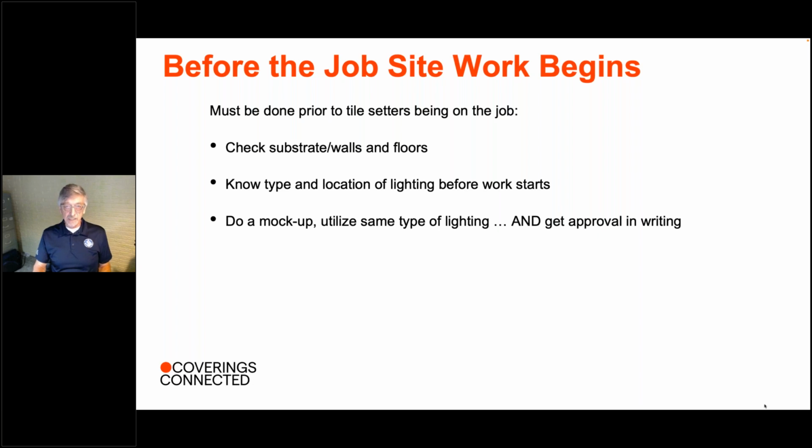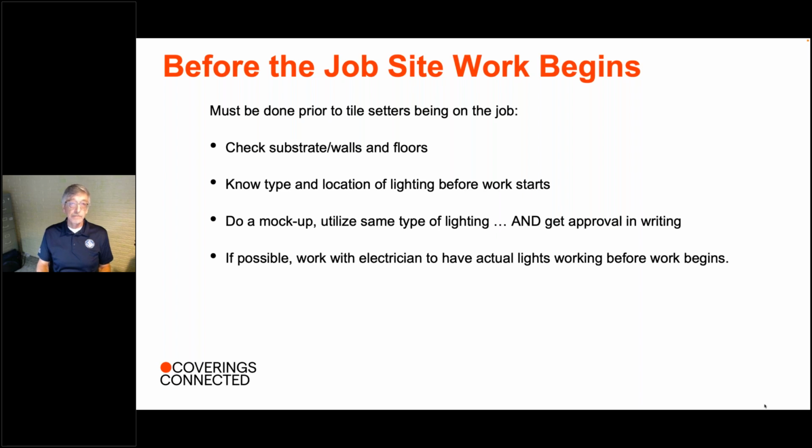We always recommend doing a mock-up and getting all the parties together that are involved with the job: general contractor, the owner, the architect, the specifier, the tile contractor, getting everybody involved to view that mock-up and determine whether or not it's acceptable, and get that approval in writing before the work begins.